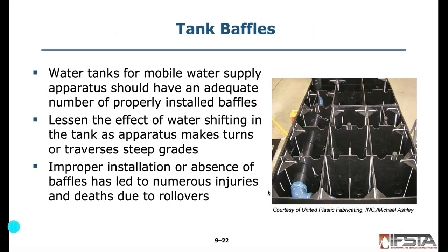Tank baffles. Water tanks for mobile water supply apparatus should have an adequate number of properly installed baffles. These will lessen the effect of water shifting in the tank as the apparatus makes turns or traverses steep grades. Improper installation or absence of baffles has led to numerous injuries and deaths due to rollovers. So that's again a safety feature that has been added to these water tenders.